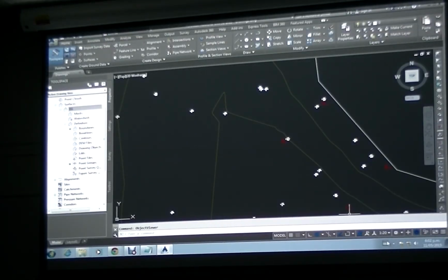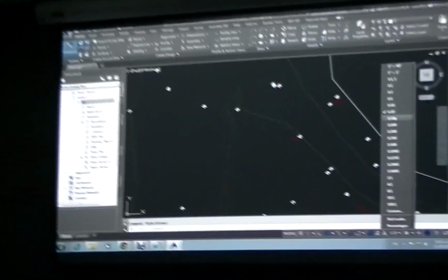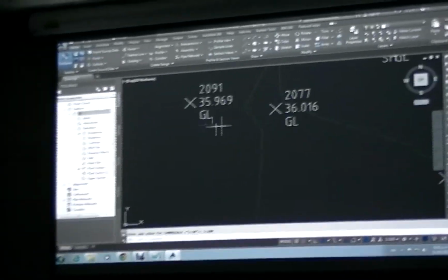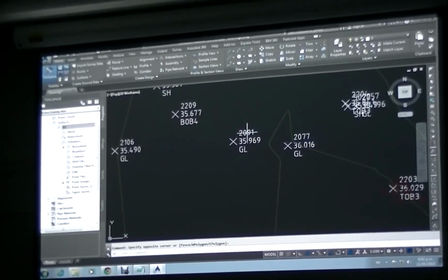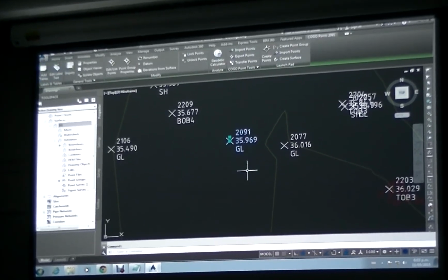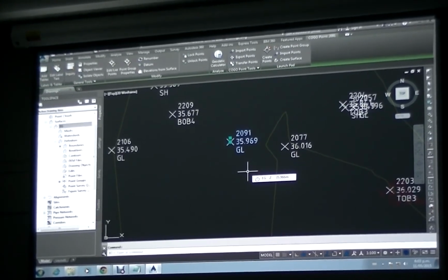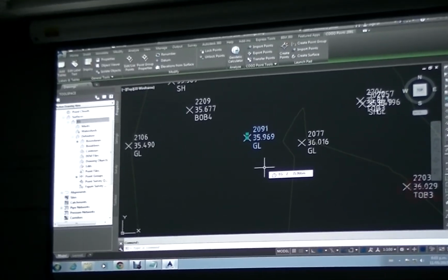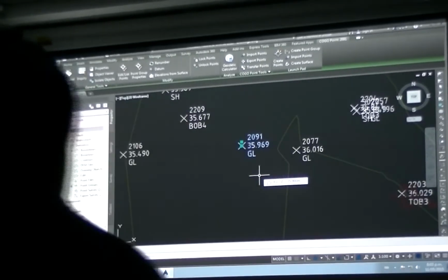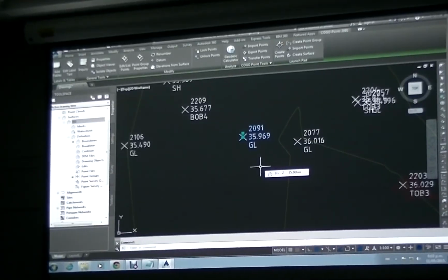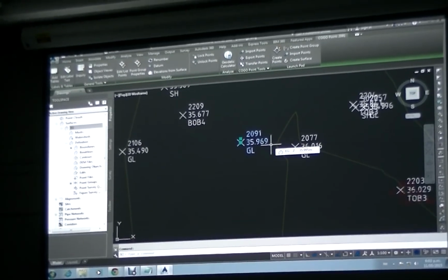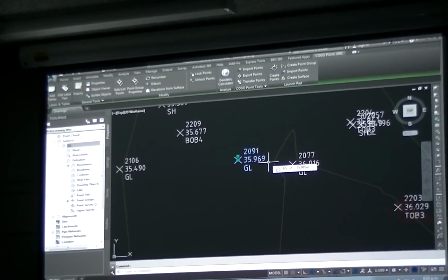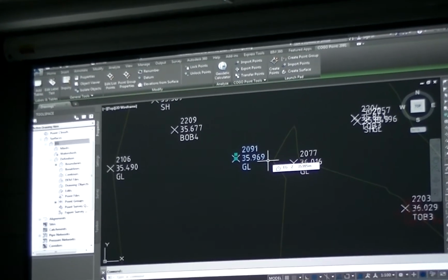So I just had a question about what everything means here. I'll just bring up the data a bit bigger. So you can see here that the point number, in this case 2019, is just the number the equipment stored the point at, okay? So the survey has just started that day's work at maybe point number 2000, and point number 19 is done that day. The next number below it, in this particular style, you've got different styles, so you can change to a different style and get different data, is the height above the datum.